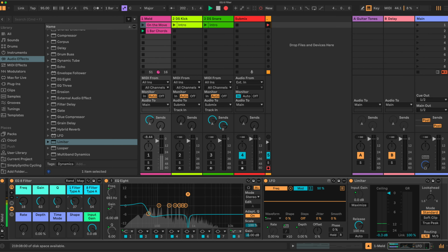And let's choose a value here so that we can make sure everything's okay. See if our Q works, gain works. Right, so with the gain and Q at maximum, with our filter 1 at 44 and this one at 29, you should have a graphic that looks like this. Anything different? And something's not right. Check that one. There we go. Okay, so they seem okay. So I think we can turn it on. Okay, so we should be able to sweep through the filters.